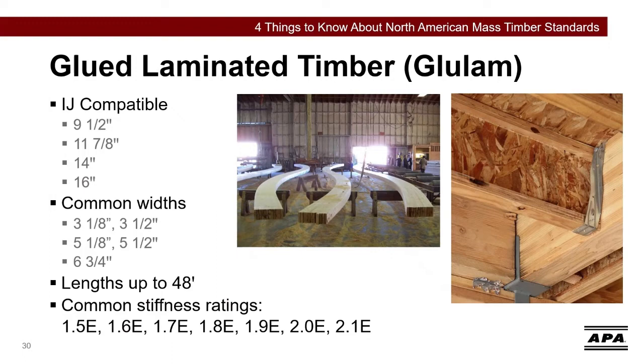Glulam are available in a variety of I-joist compatible depths. Widths to match framing are available. As with the other engineered wood products, they are readily available in lengths up to 48 feet. There are also many other sizes, and one of the coolest things, custom shapes, are available on special order.